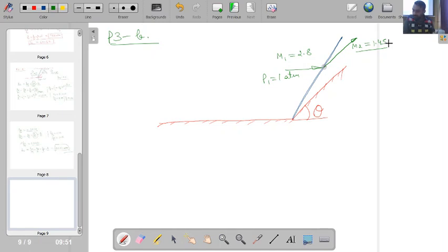So what we are considering, in the upstream and downstream of this shock wave, whatever flow conditions we are choosing, these flow conditions we are choosing identical to part A of this problem. And we are saying that this angle of deflection theta is controlled in such a way that whatever shock wave is produced, that shock wave is changing our Mach number from 2.8 to 1.45. Is this point clear? So the problem is identical to that of part A only. So flow properties are changing between the same limits, but in that case we had one incident shock wave and one reflected shock wave. Here we are trying to do this with the help of only a single shock wave.